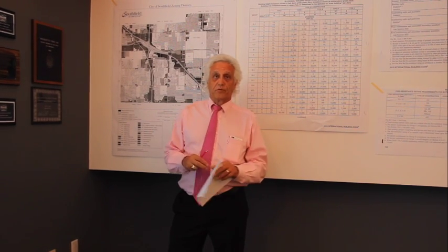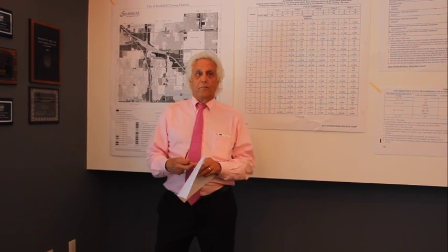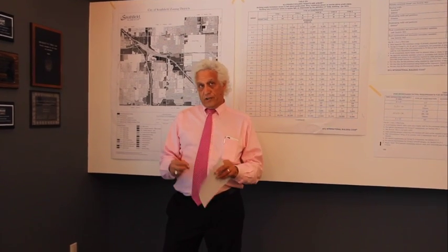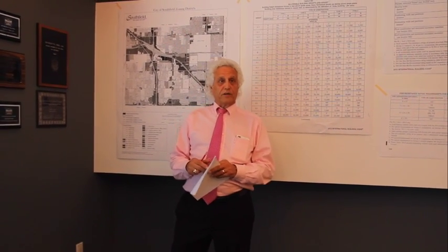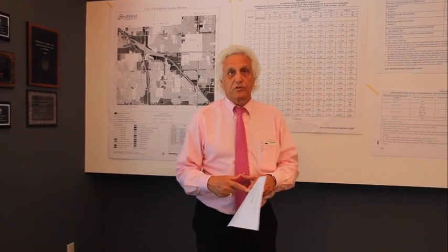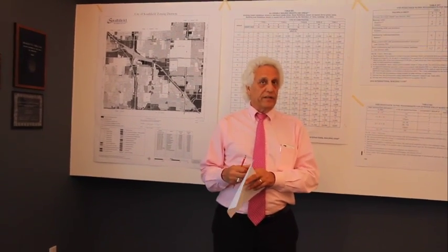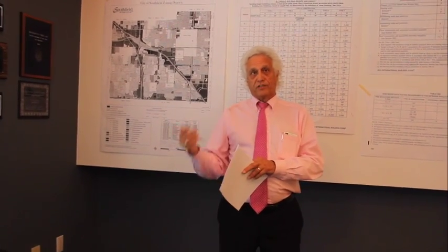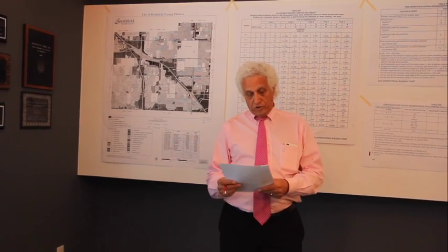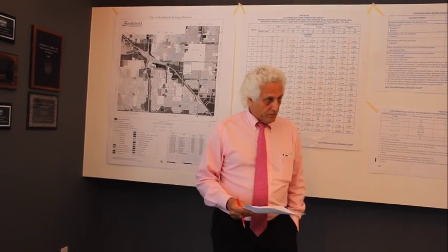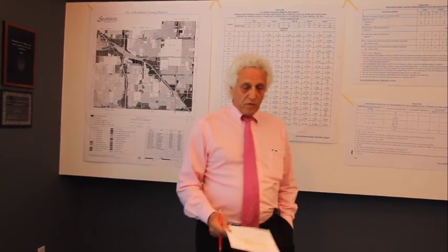The same thing with the building code. You may design a 6-story building of a certain construction type, but the code doesn't allow you to build it in 6 stories, and you're going to have to change things. There's been a lot of projects that have been rejected at the building department because they lack egress requirements or fire ratings, and all of a sudden now the project is delayed and it costs you money as well as embarrassment.